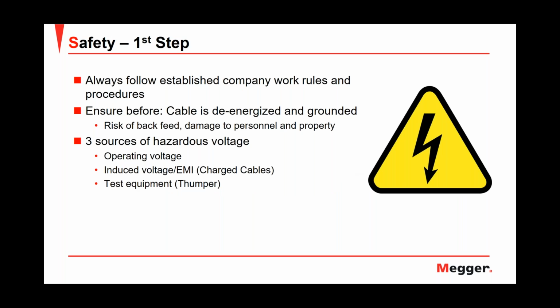Let's start with the safety. In the safety, that is the first step, as I said, we always follow established company work rules and procedures. Before doing anything, we need to ensure that the cable is de-energized and grounded. What we want to do is avoid the risk of backfeed, because the backfeed voltage could cause damage to personnel and property.